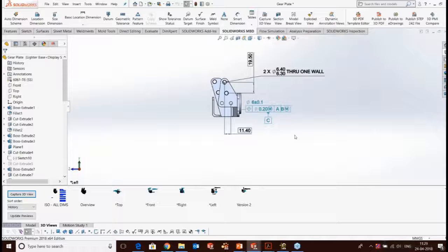That is the STEP 242. We can also now, in SolidWorks MBD, export it to STEP 242 with all the product and manufacturing information, that is the PMI added onto the model. So this is also one of the biggest advantages wherein we can leverage the complete ecosystem of SolidWorks, and we can speed up the process of manufacturing as well.